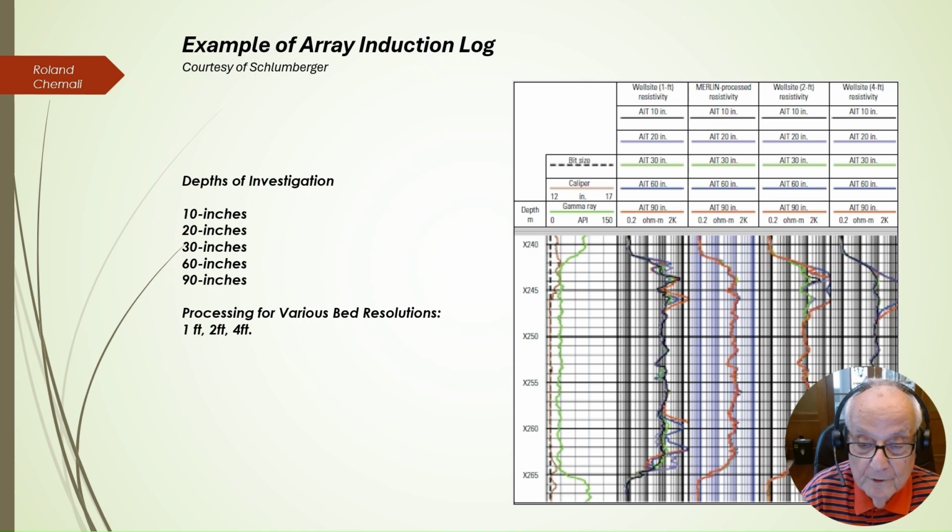So here is an example of an array induction log that I got from a Schlumberger publication. You have here the multiple depths of investigation, and you have also the different resolutions. So you get here a resolution of 1 foot, either at the well site or processed, or 2 feet or 4 feet. And you have a depth of investigation of 10, 20, 30, 40, and 90 inches. Very powerful tool.